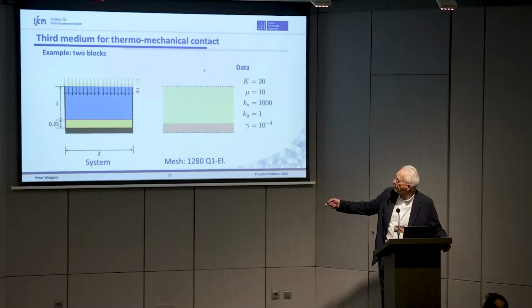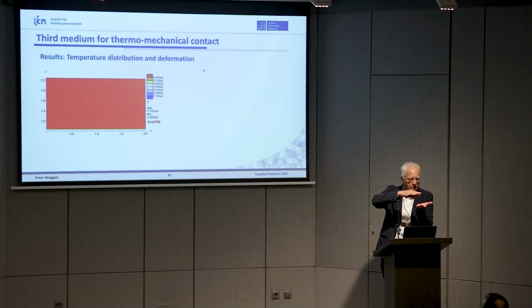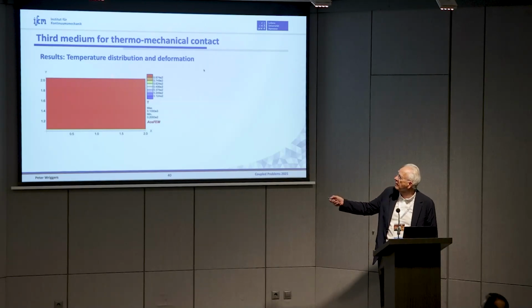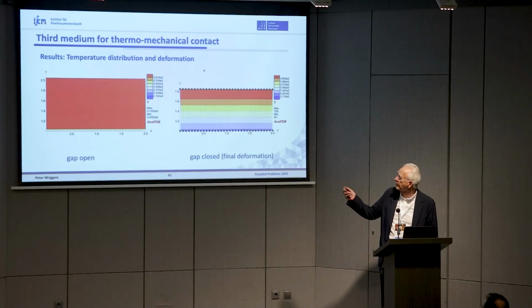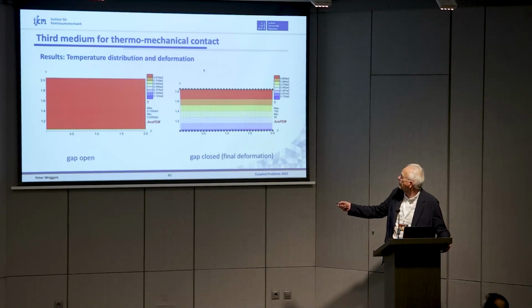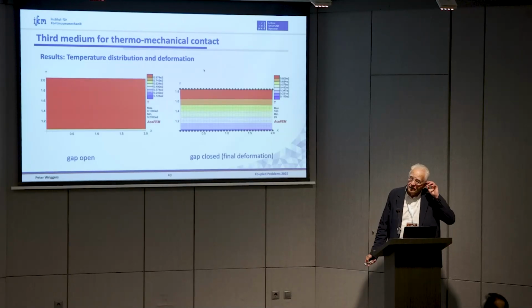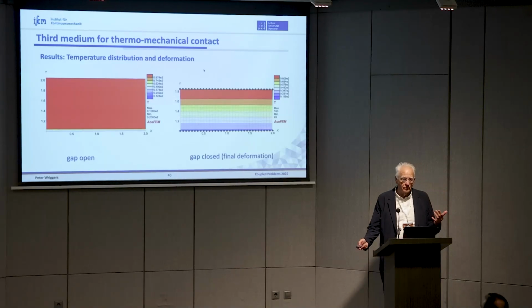So there's a difference. If you don't have contact, in the stationary heat conduction problem, only the solid has the same temperature because there is no contact yet. So the temperature stays at 100. This is the top temperature, which is now everywhere. And once the contact appears, you get the temperature distribution, which looks like this, a classical one. It was 20 degrees here, so you have 20 here and 100 there, and in between it's a linear distribution.